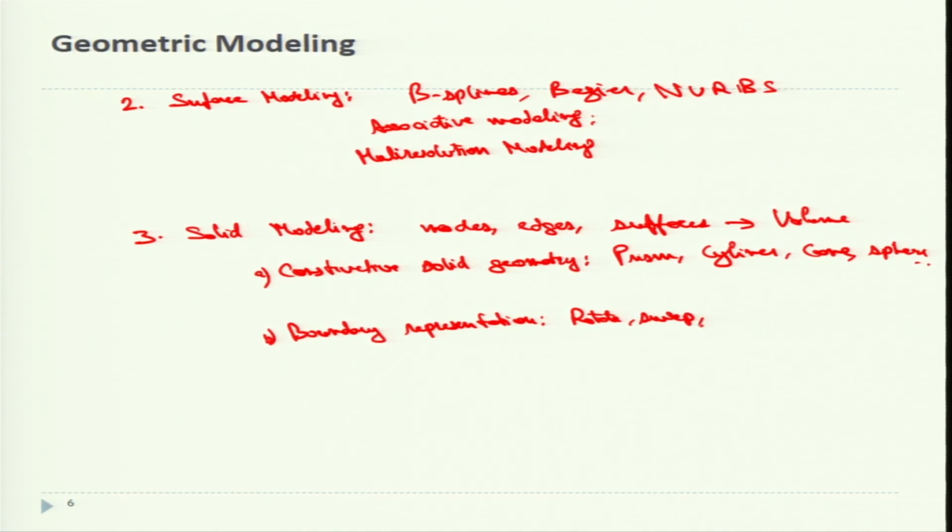Generally the CAD models that you use employ this kind of method, where you rotate, sweep, blend facets, extrude, cut, extrude various facets into the three-dimensional solid, which describes various points, edges or surfaces as a volume. These surfaces can be combined to create a surface that completely encloses a volume.